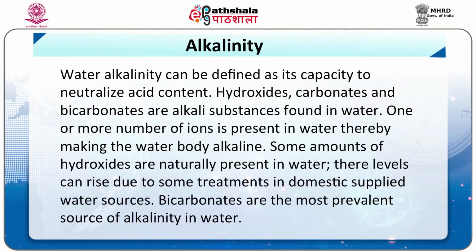Alkalinity. Water alkalinity can be defined as its capacity to neutralize acid content. Hydroxides, carbonates and bicarbonates are alkaline substances found in water. One or more of these ions is present in water, thereby making the water body alkaline. Some amount of hydroxides are naturally present in water. Their levels can rise due to some treatments in domestic supplied water sources. Bicarbonates are the most prevalent source of alkalinity in water.